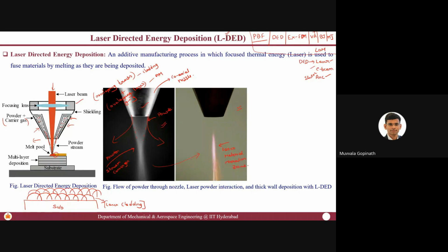So this is what we call the laser material interaction zone. Now what is happening here? Most of the energy, or some of the energy, is getting into the particles such that they are getting heated up. You can see these powder particles heated up or spreading out. And whatever is remaining after getting absorbed is actually going into what you call the substrate.